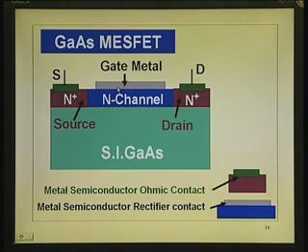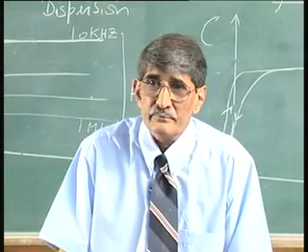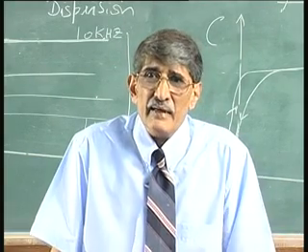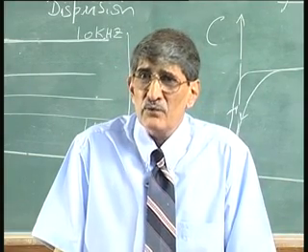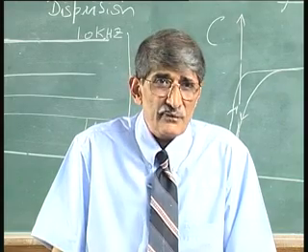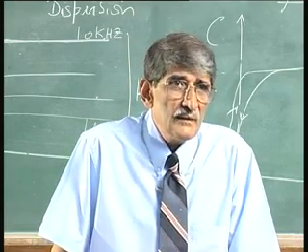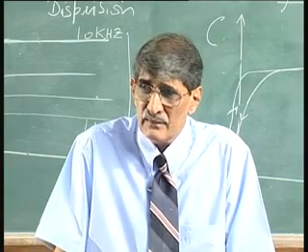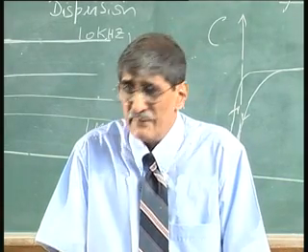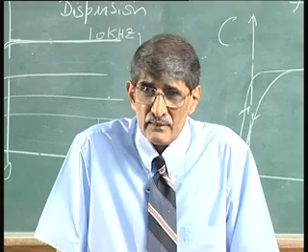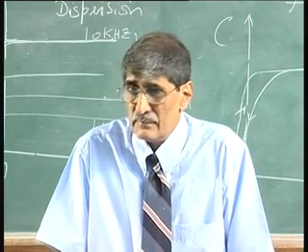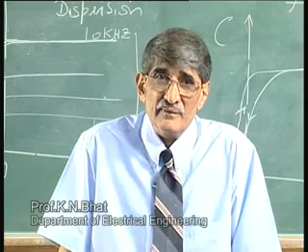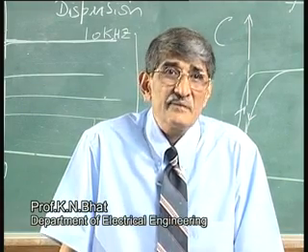So, what we said today to sum up is, we have seen that even though in silicon technology MOS has been most successful, in gallium arsenide technology MOS has been most unsuccessful. So, instead of MOS, it is a JFET or MESFET that is being used in the case of gallium arsenide devices, but in the case of indium phosphide devices you will see that it is not MESFET also.